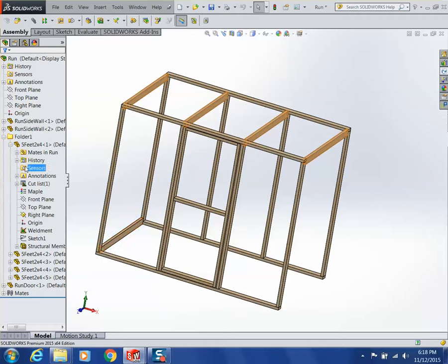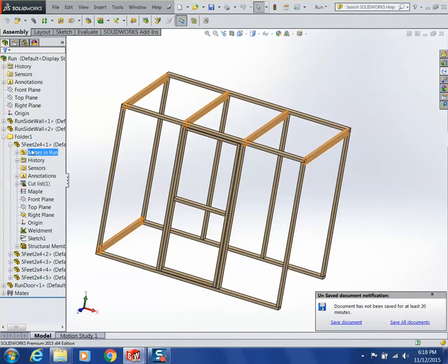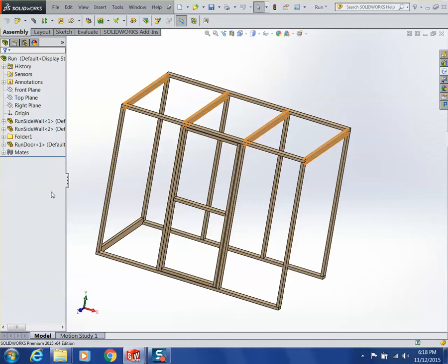One of the things that you'll run into, especially if you start using folders, you'll notice that you'll end up with a lot of stepped over things in your tree like this. Fast way to do it, collapse everything, Shift C. I don't know how many people use that. That's one of those little things that someone pointed out to me like 6 months ago, and it was like the angels sang. That was the coolest thing I'd seen in a while. Super helpful. Again, if you get assemblies inside of assemblies, inside of assemblies, which sometimes you do, you end up clicking the wrong part and magically your whole tree gets huge. You can collapse everything really simply that way.